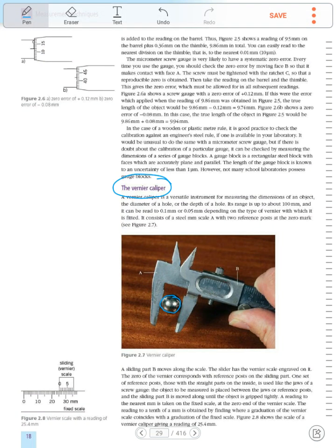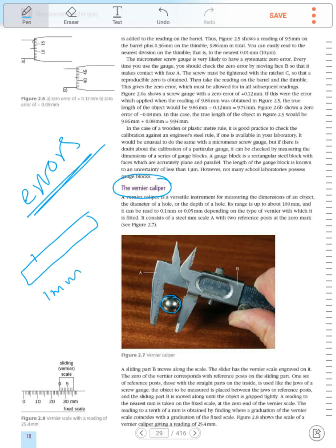You have to remember the errors in each device, okay? For a meter rule, the error is about 1 millimeter. So you have to add or subtract the error from your value. If you have, let's say, 200 millimeter, so your value is 200 plus minus 1 millimeter.